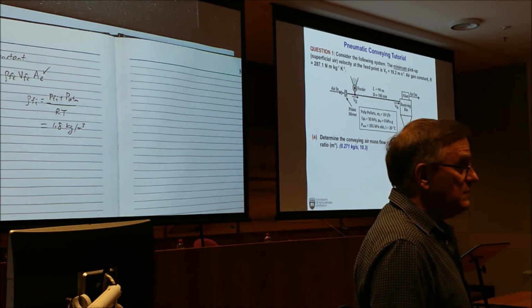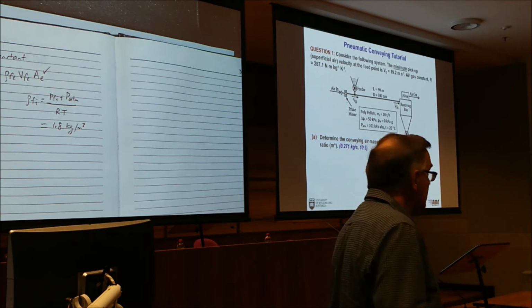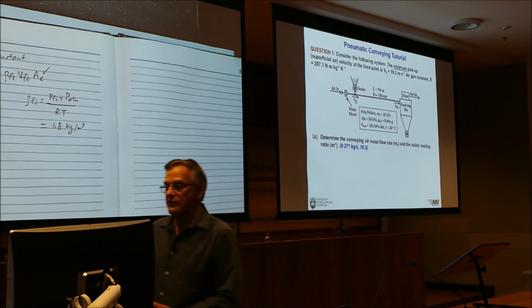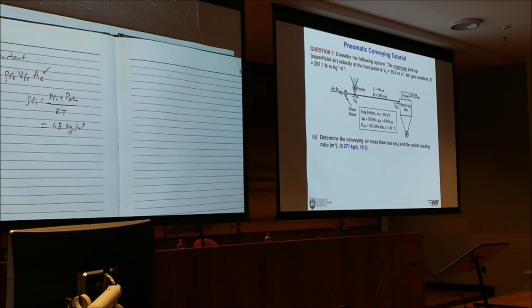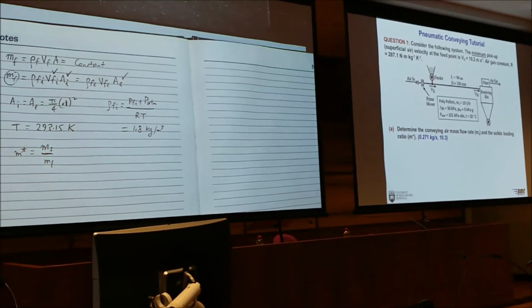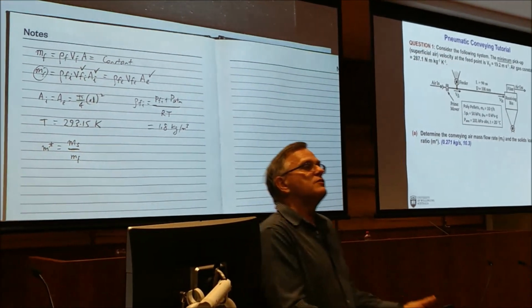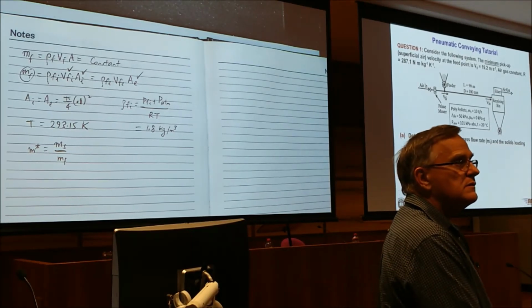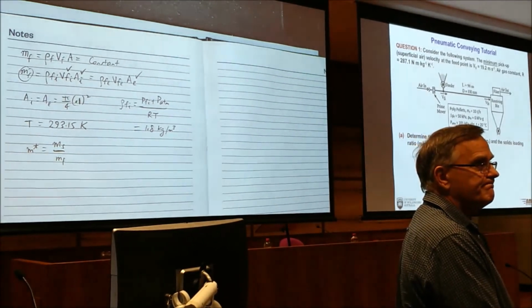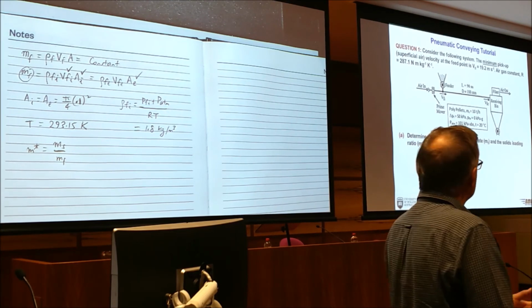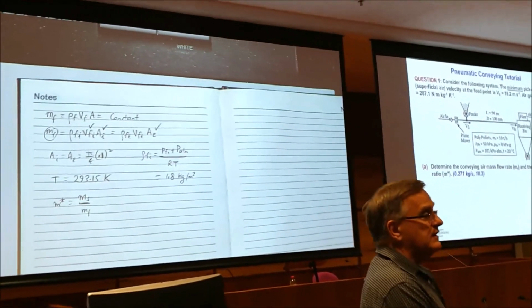Or you've got to do it the long way. Multiplied by 1,000, divided by 3,600, all that sort of business. So you divide by 3.6. So you'll get 10.3 after that calculation. That's a typical number for dilute phase suspension flow. 10 kilos per kilo of air. It can be less than that, not often bigger than that. So you've got to understand that M star.